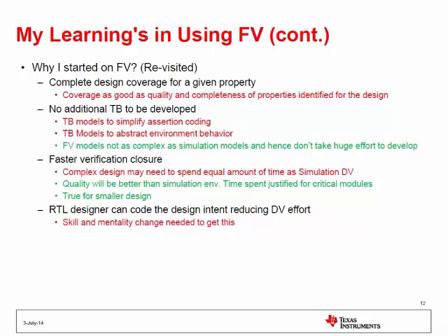So that's where you still see, even though you're developing models, it is not a complete whole flow that you're doing. Again, another notion that we say is, okay, I get a faster verification closure. This again is false, because with complex designs, once you start applying FE, you will need to spend a lot more time than what you do in simulation-based verification. But the quality you get is definitely better, and that's why I keep stressing the point: you need to know where to apply FE.